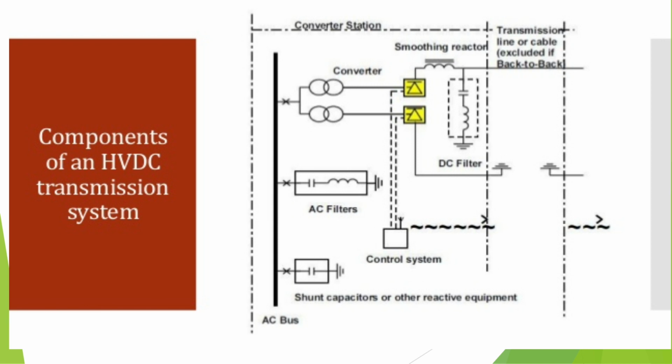If you are not eliminating any harmonics in the system, it will definitely cause interference in the telephone lines, and due to the presence of these harmonics there are power losses in the machines. That means the system is unstable. That means instability of converter controls. So it is necessary to minimize these harmonics by using AC filters as well as DC filters.